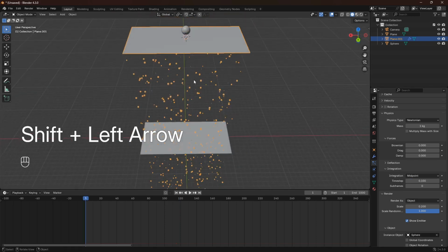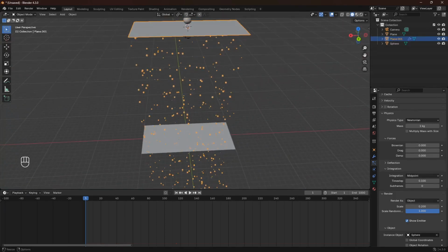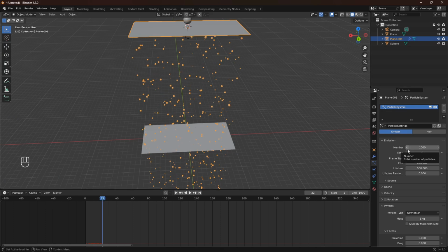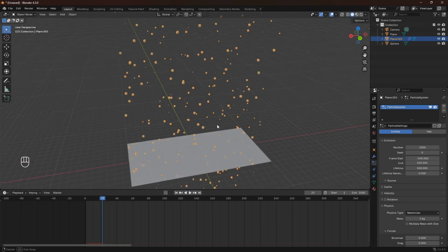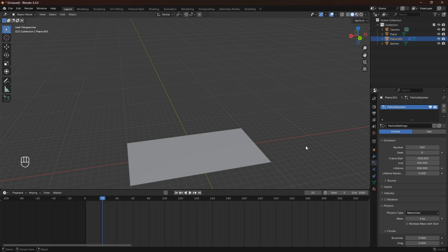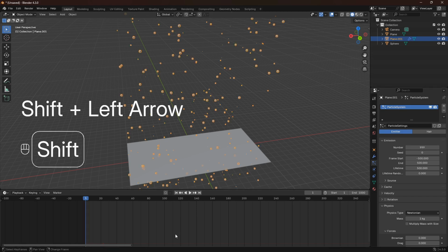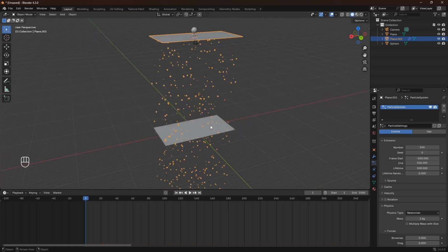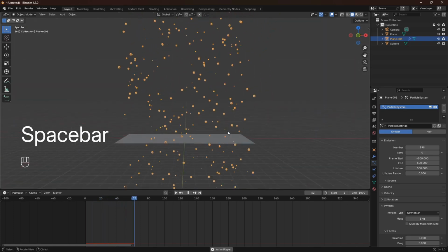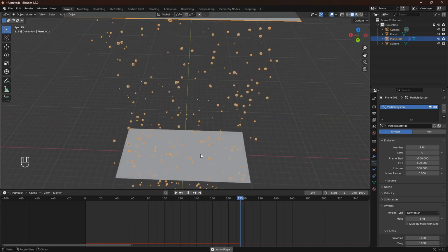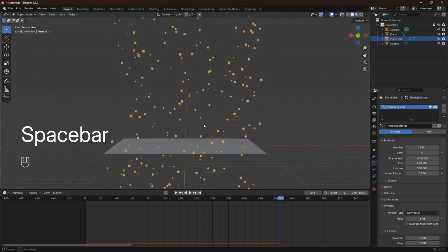And by the way, if this particle system here is hiccupping, what you want to do is go into the numbers. This is just, I don't know, maybe a bug or something, but you need to change the number like that, and then go into the timeline and set the particle system to the first frame. So if it hiccups, go and change the number and then bring it back to the first frame like that. So now we have these particles coming down, and the thing here is this is completely overload for this ocean plane that we are going to make.